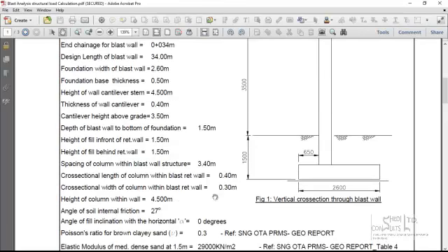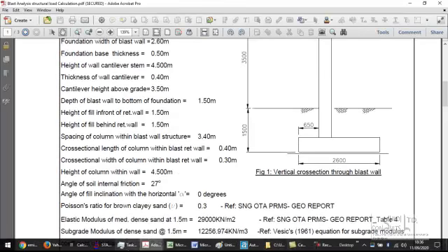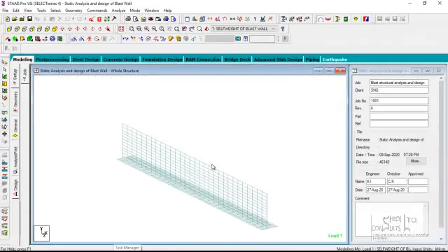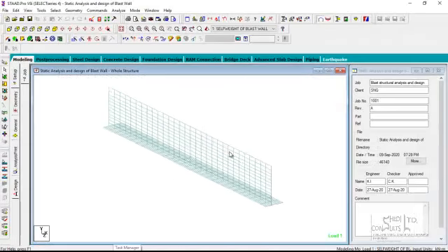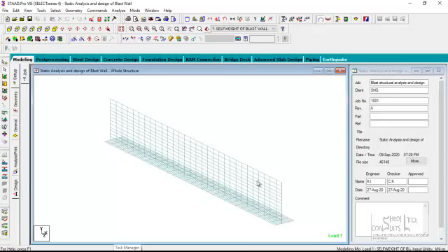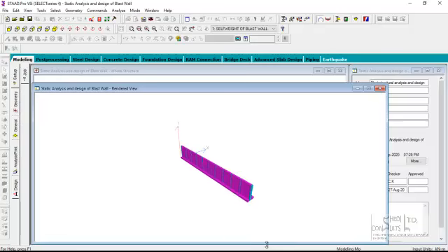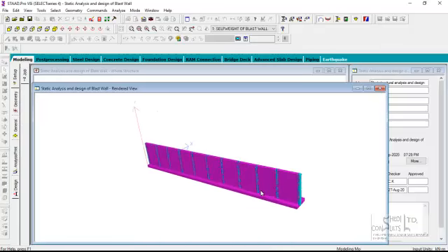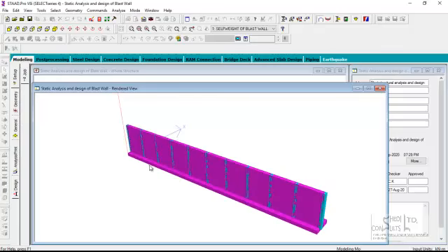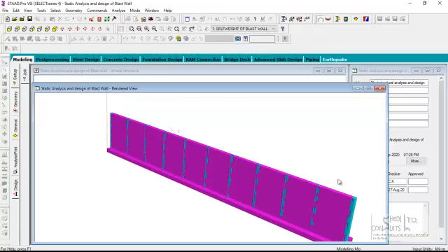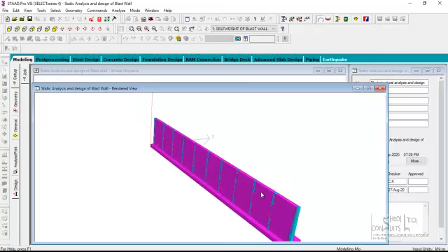Now this wall is designed to have columns in between. Because of its length and the corresponding blast loading that was calculated for the shock front and its side, to prevent catastrophic failure of the wall, it has columns in between.